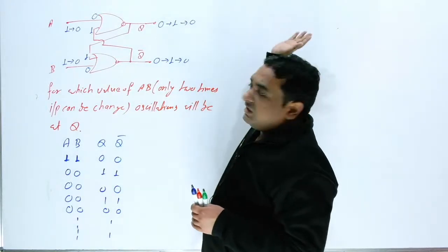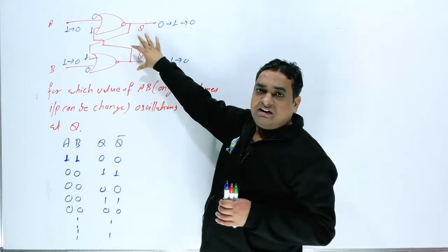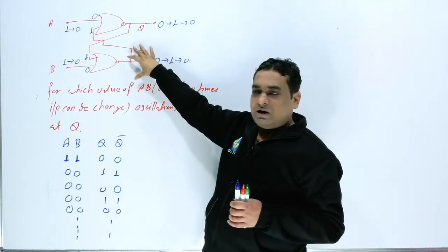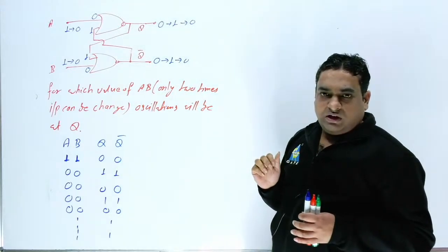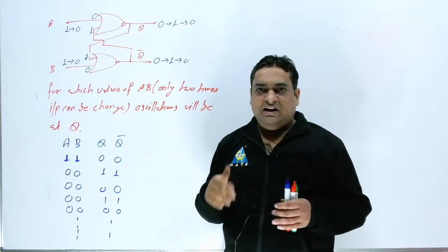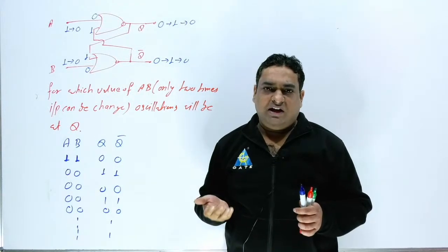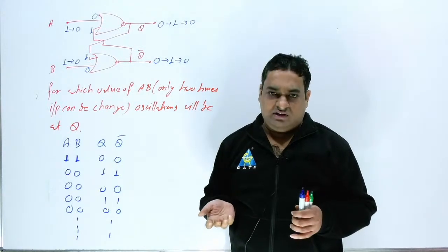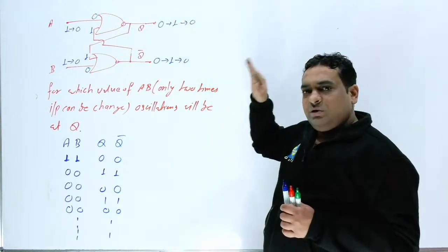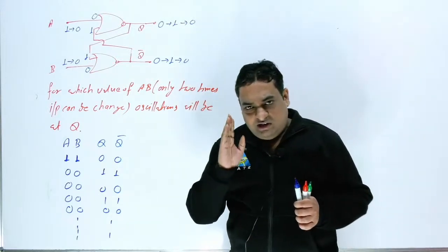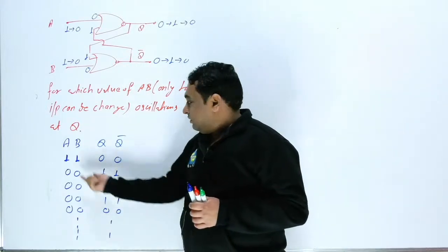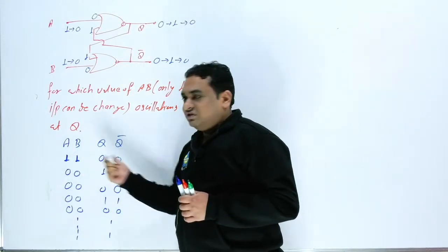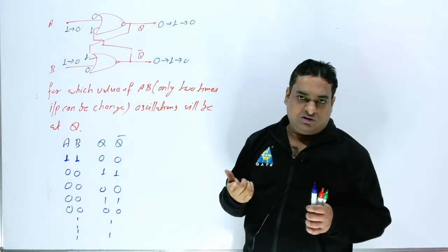If your previous circuit was the active high SR flip flop, you can say this is an SR latch, the active high category of SR latch. And a cross coupled NAND gate circuit is the active low category of SR latch. But if you design the active high category of SR latch using NAND gates, for the same answer you should get 1 1 first and then 0 0.